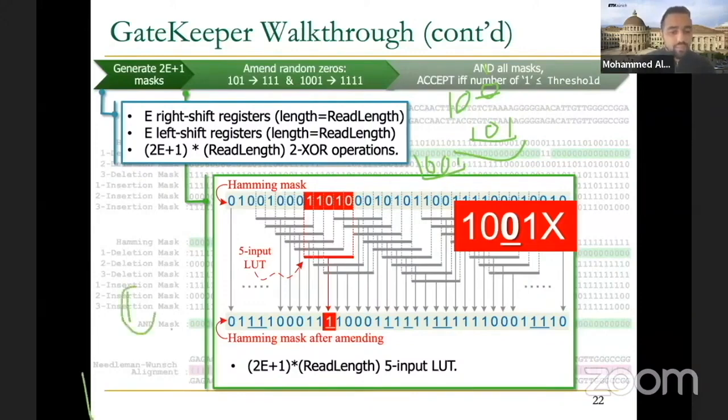Imagine this case, we have 0, then 1, and now we start counting. 0, 0, and then you don't have anything to check because that is 4 bits. How about this case? Is it correct or not correct? We don't know, because here you may have a 0, you may have a 1, right? So we still need to check the 5th bit over there. That's why we consider 1, 0, 0, 1, and then something else, or don't care, next to it.